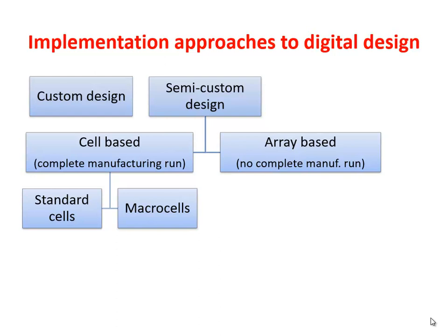And the other type of semi-custom design is the so-called array-based design. The specific thing of the array-based design is that one does not need to do a complete manufacturing run. For example, in those cases, you can have a situation in which the front end has been already done.